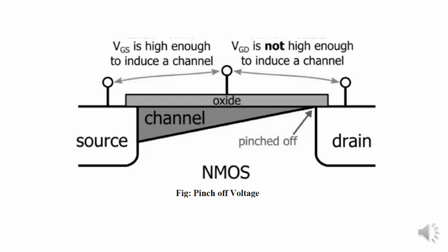However, near the drain, the gate and the drain jointly determine the electric field pattern. Instead of flowing in a channel beyond the pinch-off point, the carriers flow in a subsurface pattern made possible because the drain and the gate both control the current. In the figure, the channel is indicated by a dashed line, and becomes weaker as the drain is approached, leaving a gap of uninverted silicon between the end of the formed inversion layer and the drain. That is the pinch-off voltage. And also, as the drain voltage increases, its control over the current extends further towards the source,